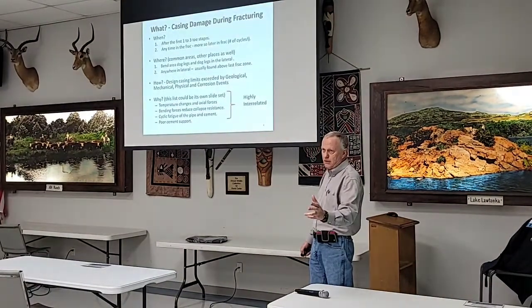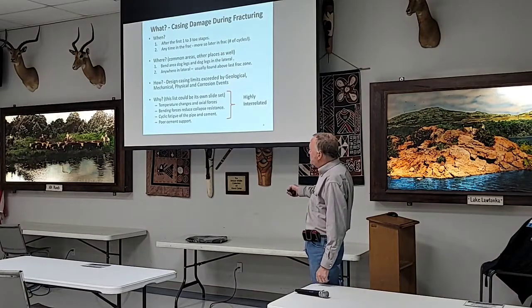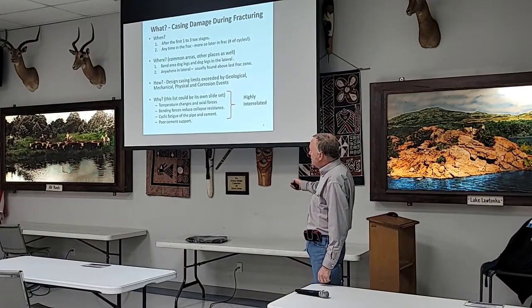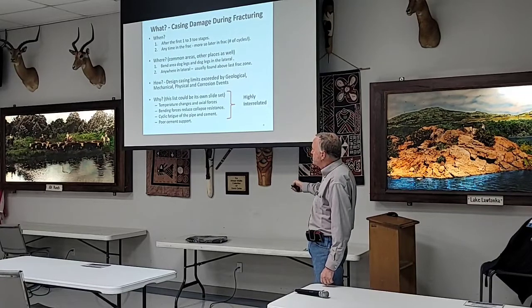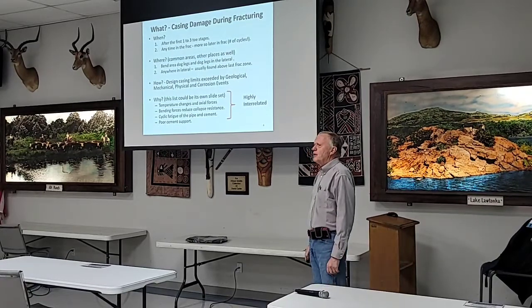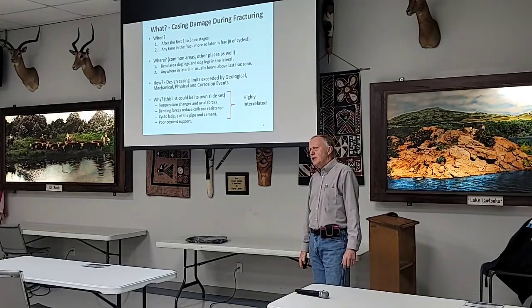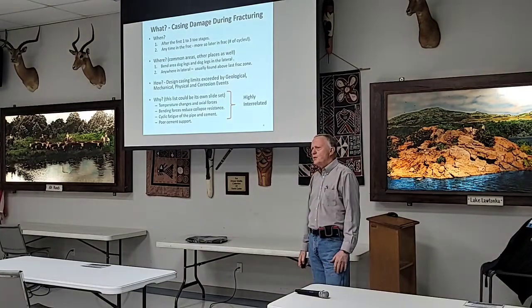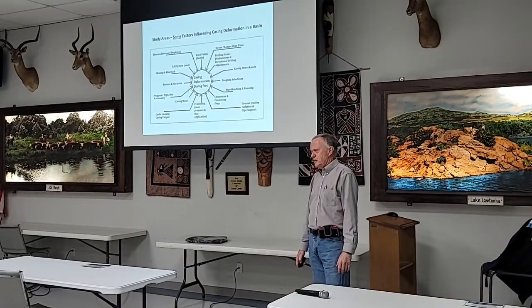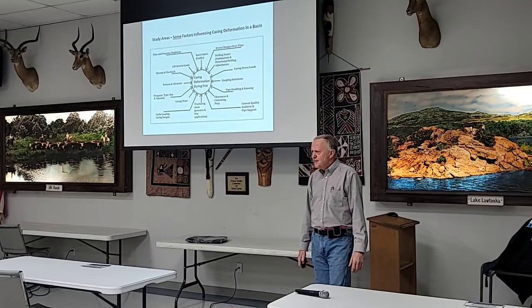And that's what's hurting you. Now, the last thing here is really poor cement support. And I have to go back to this almost every time, because if you have a really good cement in these wells and you do have a smooth well bore, you rarely have problems with this. So it can be a factor.